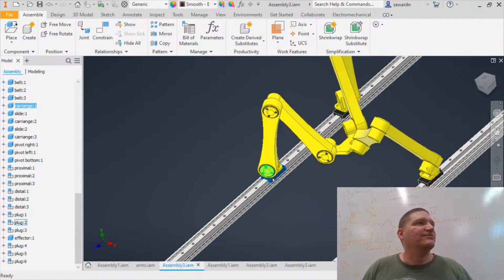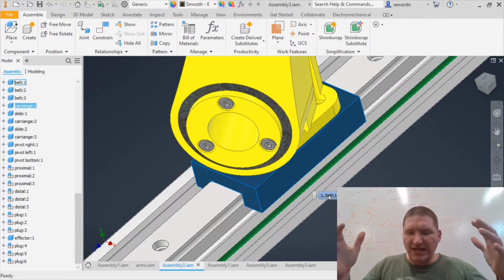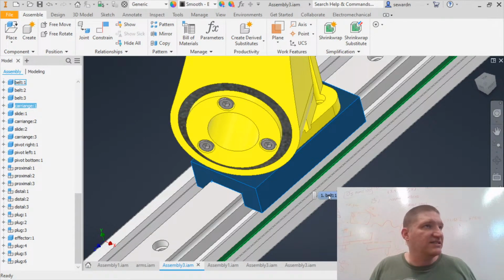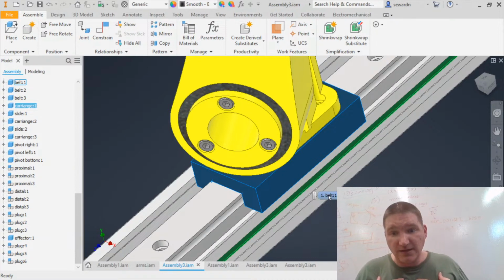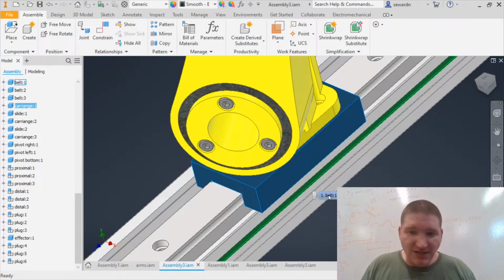And I don't have it shown here, but I'd put a little piece of plastic underneath this, and it would reach down and grab onto the belt. The belt would not be a continuous loop. It would have ends, and you could bring it out and use that for tensioning, yada, yada, yada. So that's how I'm planning on driving this. I know there's a million different ways to drive this. Belts and stepper motors are very easy, cheap, fast, proven. So I'm cranking out a prototype. I'm going to keep it all pretty basic.